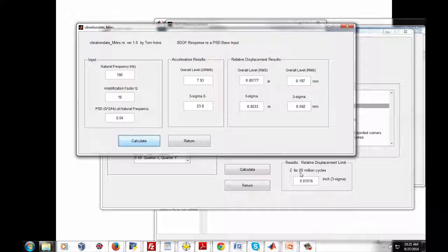Now for my design rule of thumb, here's what I'd recommend. My ideal avionics box has a very stiff circuit board inside. But on the outside of the box housing, that same component is mounted via soft isolators or bushings or grommets, whatever you want to call them. That will take the natural frequency of the box itself down to a very low frequency, so it will attenuate the shock and vibration that propagates into the board. But once that attenuated shock and vibration does propagate into the board, that board is so stiff that its relative displacement relative to that incoming excitation will be negligibly low.